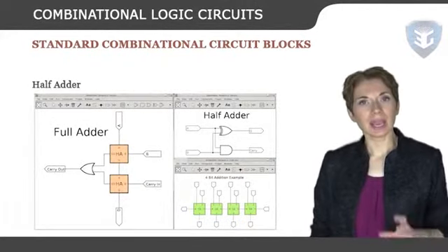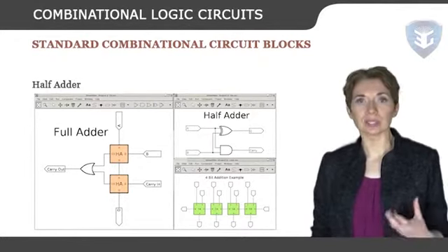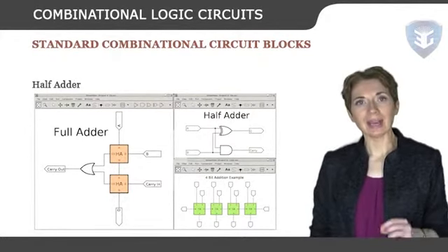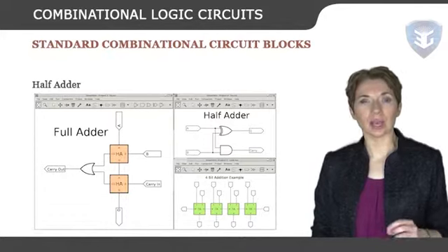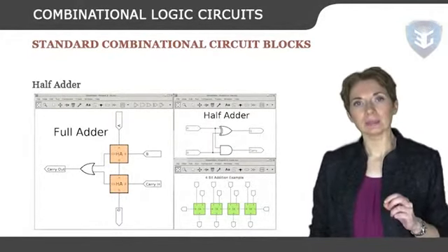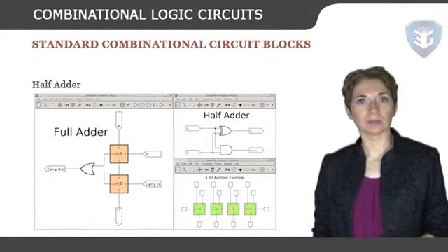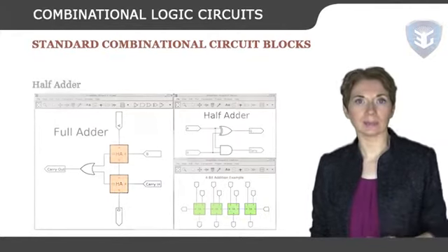Half-adder. A half-adder is a combinational logic circuit with 2 inputs and 2 outputs. The half-adder circuit is designed to add 2 single-bit binary numbers, A and B. It is the basic building block for addition of 2 single-bit numbers. This circuit has 2 outputs, carry and sum.